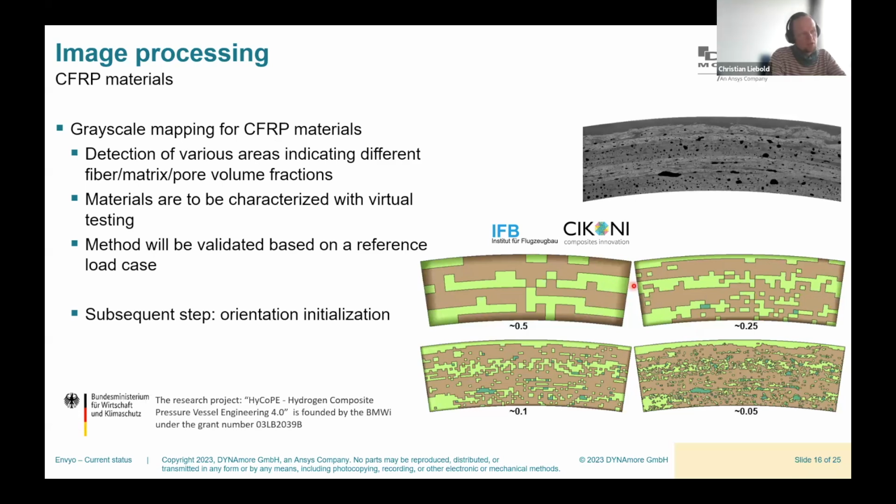The finer the mesh, of course, the more accurate you are. If we look, for example, in this area, we can at least see to a small degree that there seems to be a shift in orientation. We do have some matrix-rich zones in this upper area, so that's what's being represented up here. We also see the weaves of the rovings, actually, and we can detect pores.